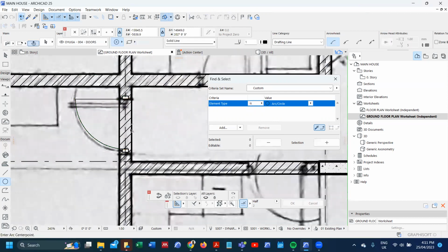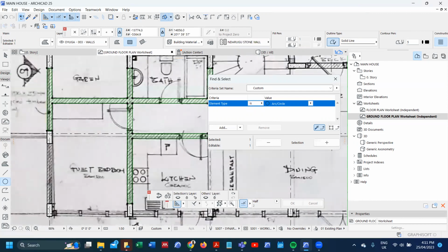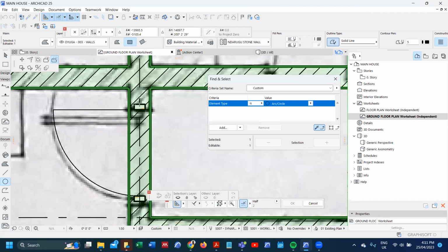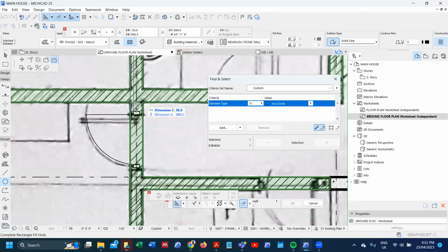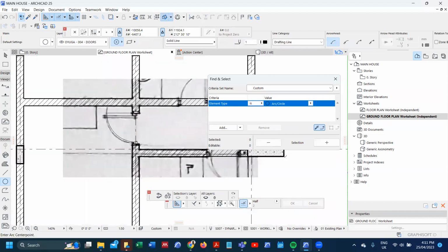What does that mean? It means that the extent of my wall that's touching the door needs to be cut off. Now, if I split as a consolidated fill, a number of things will go bad. So all what I need to do is to use the subtract tool and subtract from that point. So with that, I'll have placed my door.